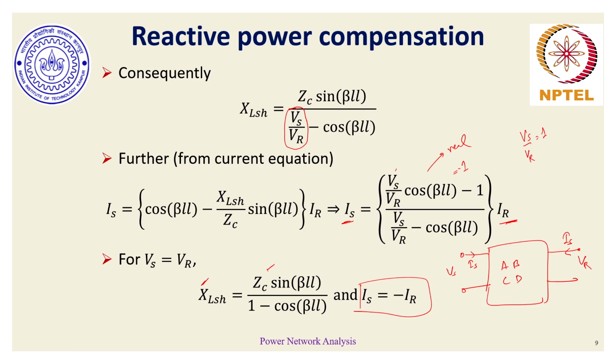So one would wonder or assume that if we have IS at the sending end and also IS at the receiving end, then there might come a point somewhere in the line where, by KCL, since the line is perfectly represented by ABCD parameters, which we can represent by the corresponding pi model or T model, there might come a point, usually midway between sending and receiving end, where by KCL the net current would be perfectly zero.